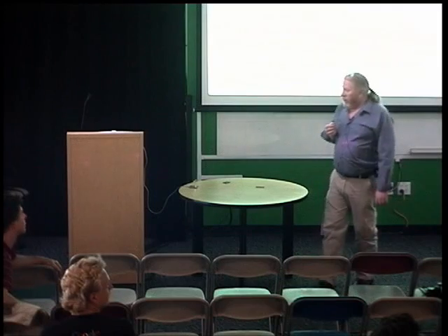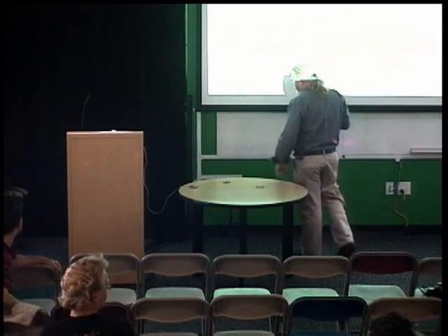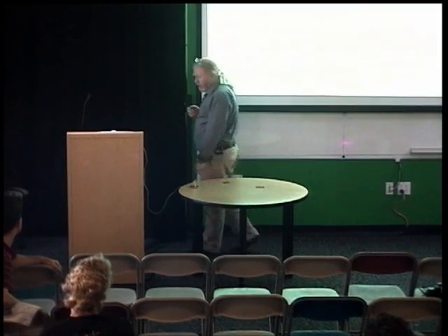I was wondering if you could say a few words about antenna design, what sets the scale, what sets the shape, that sort of thing. Well, in the end, it's a trade-off between the kind of band. This one you see here, the first one we made, was a little low in frequency, 2.5 gigahertz center frequency, fairly wide band. So it's not within the bandwidth defined by the FCC as it is now.